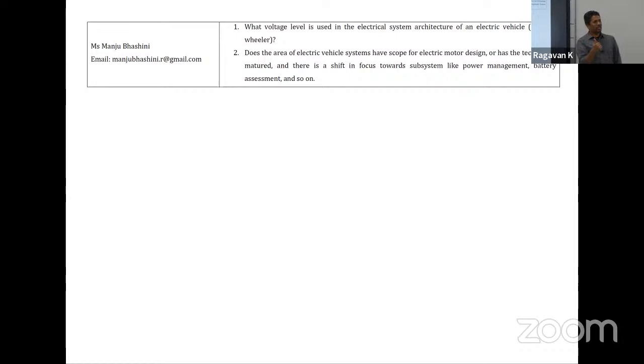Either you could have fewer cells in series and then a DC-DC converter, or you can have more cells in series with a more sophisticated BMS system and then skip the DC-DC converter. But that means now high voltage, high current, so your pack can be a little more cumbersome in that regard. But the 48 volt system definitely is making its way in at this point. That's been around for some time now. It's not like the 42 volts, it hasn't gone anywhere.